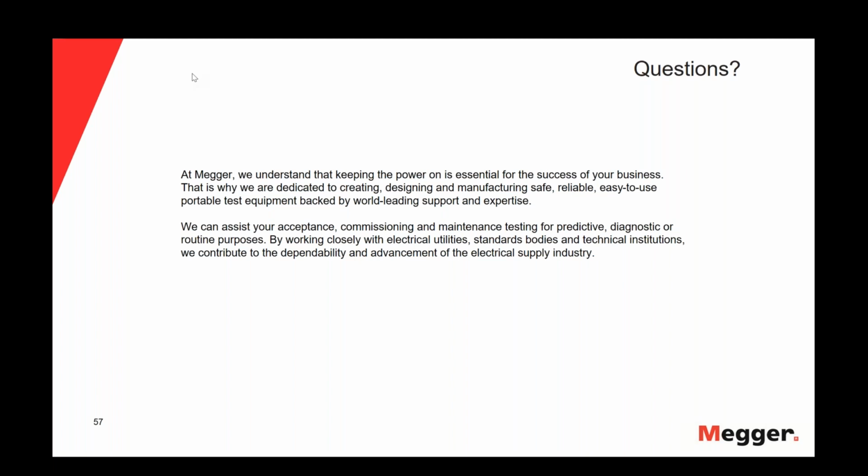And this is a kind of a Hail Mary. So everything failed. They started with the normal test. They knew it was a troubled cable. They reduced it to 2U0. It failed during the 60 minutes. Now they do 1.7 for 5 minutes, and hopefully it passes. And now understand this: this is not really a proper withstand test anymore. This is just, oh, we have a really troubled cable, a bad cable.